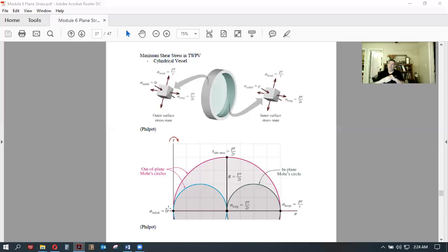For a lot of metals, that's about a 60% value, and you ultimately tend to look at things from the tensile perspective because the yield is high enough, even with the kind of thing that you're seeing here, where the absolute maximum shear stress is one half of the absolute maximum tensile stress. But if the yield strength in shear is 60% instead of 50%, it's even bigger, then you're going to be dominated by the tensile behavior.